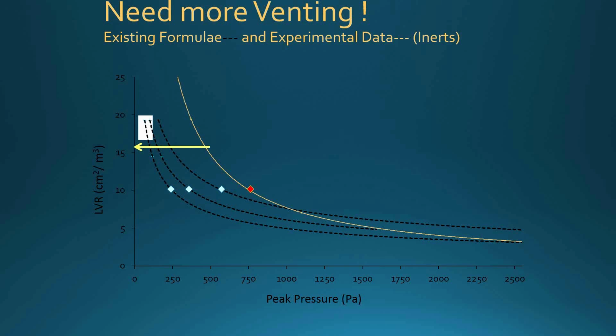So there is a 100 to 400% error in a lot of the peak pressure formulas that the manufacturers are providing, not because they don't know how to measure pressure, but because the relationship between how we measure the leakage during the test, during the research, and how we measure the leakage in the enclosure when the enclosure integrity tester goes out there were different.